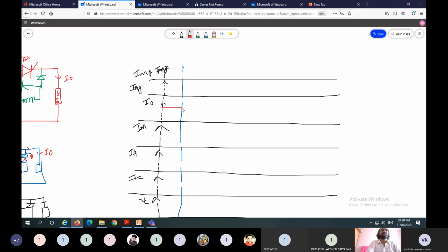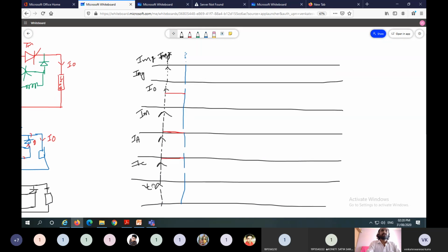This one is load current. And in this time period, main thyristor is off state, so main thyristor current is 0. And also auxiliary thyristor is off state, so auxiliary thyristor current is also 0. Next, capacitor current increases.